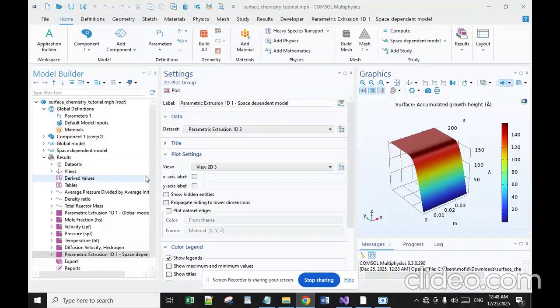CVD employing a high density, low energy plasma to obtain epitaxial deposition of semiconductor materials at high rates and low temperatures. The next one is atomic layer CVD, which deposits successive layers of different substances to produce layered crystalline films.